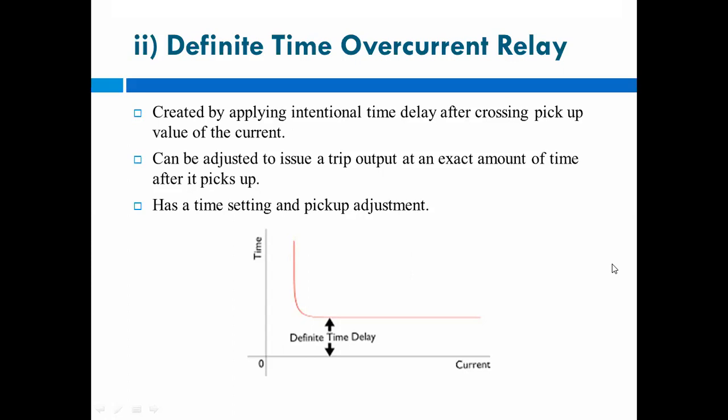It will sense the fault, but it will actually operate at 0.5 seconds. That is the definite time overcurrent relay.